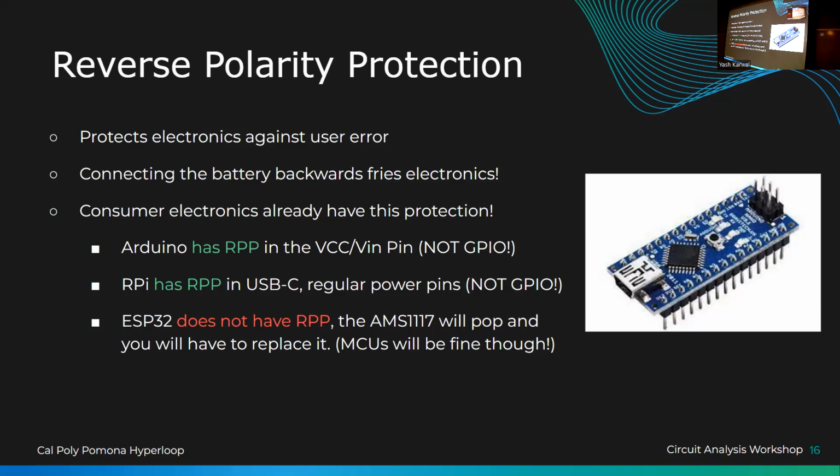If you include a diode in your circuit, it'll basically prevent any current from flowing the wrong direction, so if you do reverse polarity. But if you have too much current, there's also a chip that can detect that and just shut off the circuit for you. But like Maggie said, it's generally a transistor that controls the power going to the circuit. If there's something wrong going on, it'll just break, so it won't allow any current in the circuit. And when things are fine again, it'll connect back together. The next slides do show different ways you can connect the circuit.